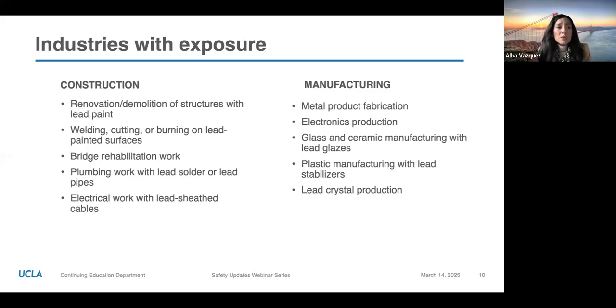And so we really need to be aware of those safety data sheets and what is the actual lead content, and start asking questions and finding out what are the materials this worker is going to be interacting with, or scraping or sanding or doing manual demolition with, so that we start looking into, is there any data or information out there that can help me find out what is the actual exposure.